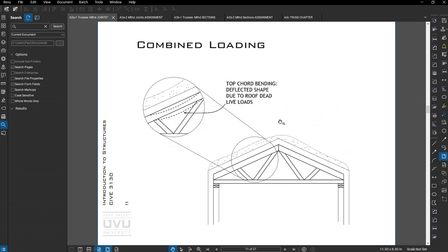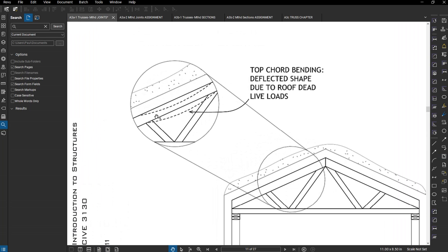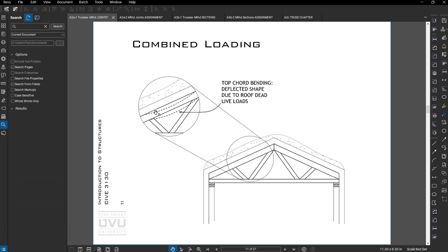Another thing we need to take into consideration is if our truss has loads along the length between the panel points. So at the nodes here or panel points, normally in a truss we assume the load gets applied right at those intersections. But let's say you have a roof with snow on it, that member will actually also have bending like a beam in it. Turns out that can make your member size 2 to 3 times larger just to carry that bending stress.